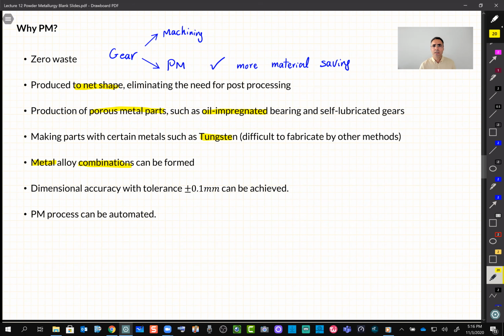But with powder, you can easily mix, let's say, gold and titanium. You mix it because they are in the form of powder. And later when you sinter it, of course, you make sure to sinter it at a temperature considering the lower temperature one, to create the bonding.